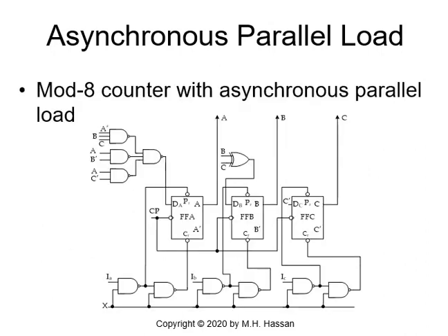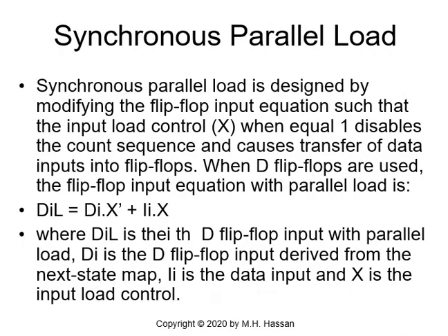Okay, now let's look at synchronous parallel load. The synchronous parallel load is designed by modifying the flip-flop input equation such that the input load X, when equal to 1, disables the count sequence and causes transfer of data to the flip-flops. We can do this simply, for instance, in the D-type flip-flop, where we have D1, D2, D3.